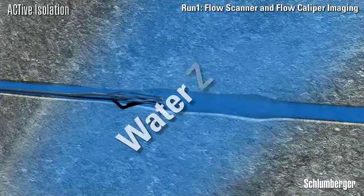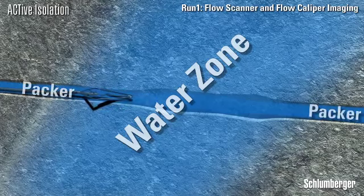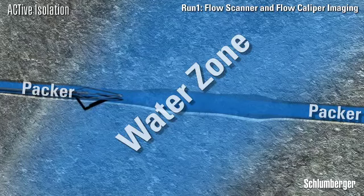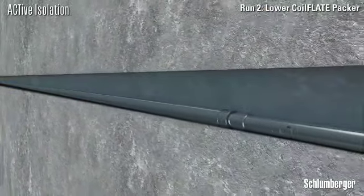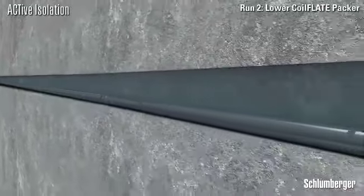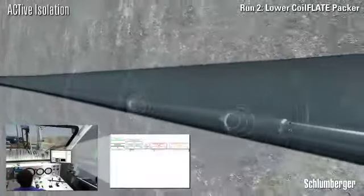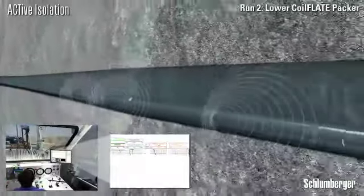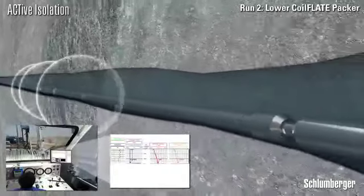Interpretation of logging data allows water zone identification and wellbore geometry evaluation to determine the best packer set depth in the open hole section, where wellbore ID and ovality are ideal. While a second run takes place with active downhole measurements, pressure, temperature, casing collar locator, gamma ray, and tension and compression, the CoilFlate inflatable packer can be depth correlated in the casing by CCL and in the open hole by gamma ray in real time.